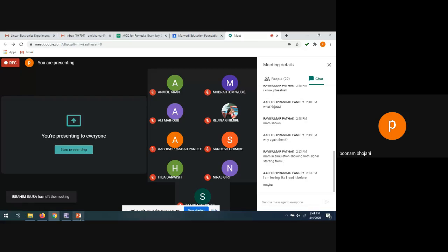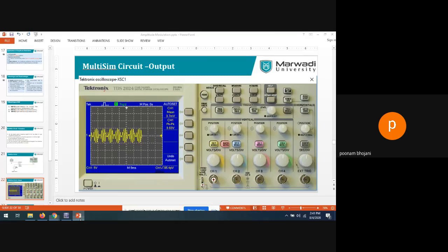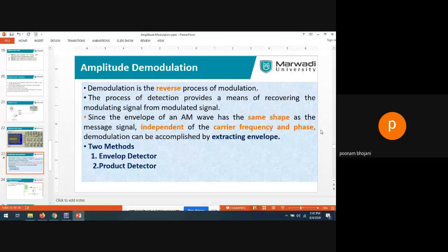Now, the demodulation. Demodulation is equally important. Before doing the demodulation, let me tell you there are so many techniques to do the demodulation, right? But those different demodulation techniques are for the different forms of AM. For DSB-FC, there is a different demodulation technique. For DSB-SC, there is a different technique. For SSB, there are different techniques. So here we are going to see the demodulation for only AM. AM is equal to DSB-FC, double sideband full carrier. How this signal will be demodulated to the original message signal at the receiver side, that we are going to see here.